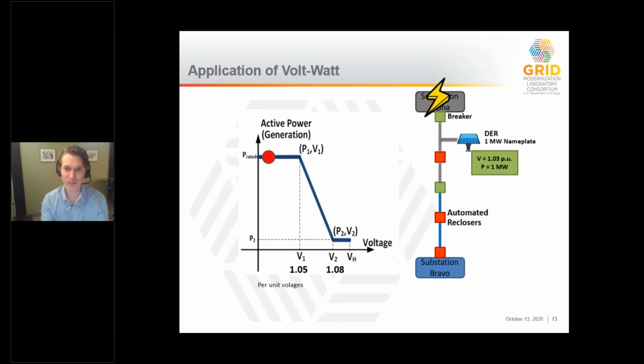So the fault is isolated. Next slide, please. And our DER is re-energized now from that blue substation at the bottom. But now the DER is so far away from the blue substation. Next slide, please. We have the potential for a high voltage. So let's just assume that the voltage goes up to 107% of the nominal voltage.